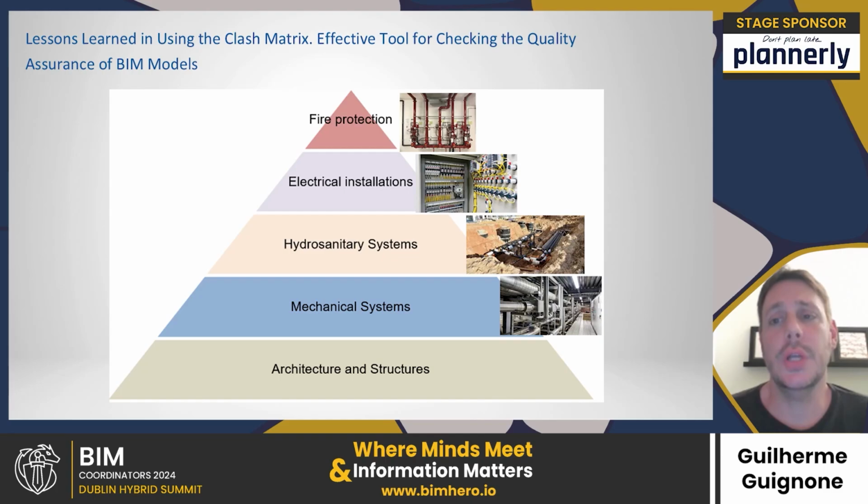Mechanical systems usually have components with larger dimensions, which present greater space restriction and provide great impact when changing them. If there is interference between the sanitary system and the electrical system, the electrical system must be changed because in most cases it has smaller dimensions.